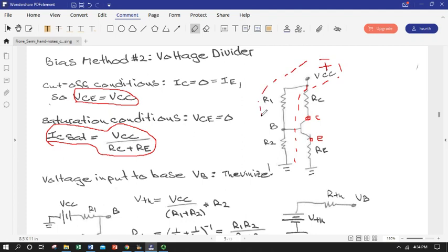We're going to Thevenize around point B. Remember, a Thevenin equivalent is an equivalent series voltage source and resistor in series that are taken from the point of view of the component or the point in the circuit around which you are Thevenizing. So it all depends on the point of view.